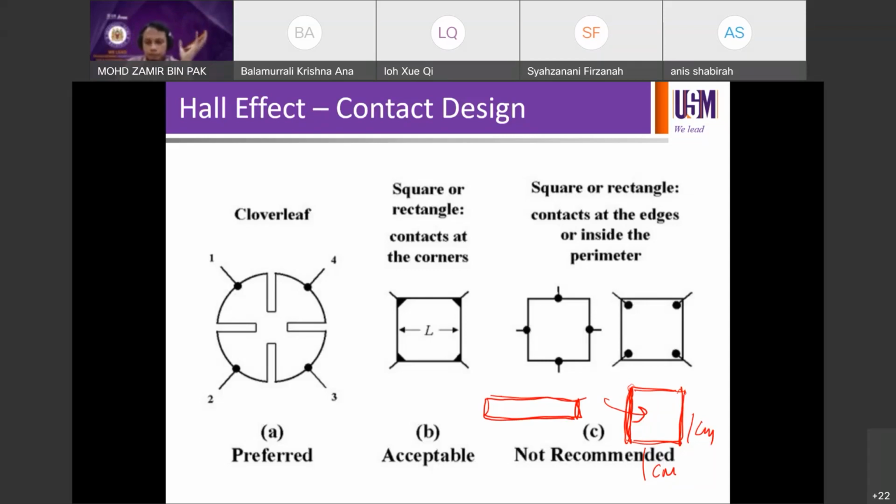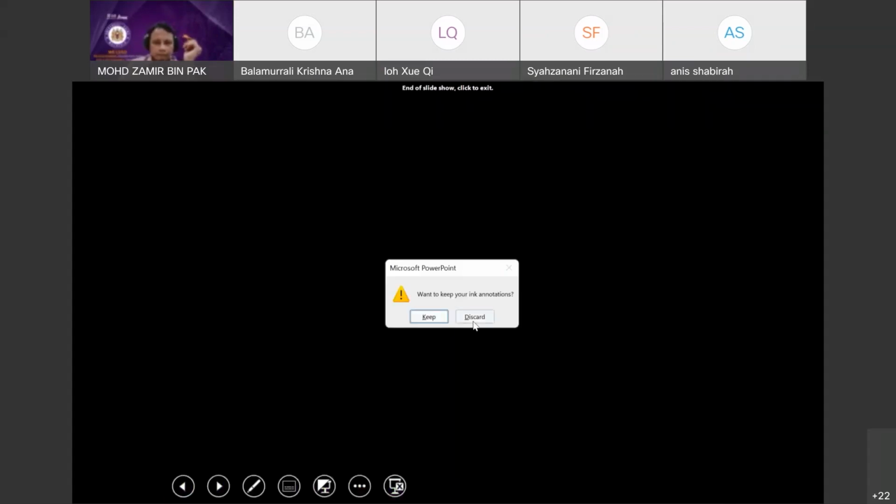So typically, if you have a square sample like this, you need to evaporate, or incorporate, the metal contacts on the sides, on the edges of the sample. For example, say your semiconductor here is silicon, so you might want to evaporate or use some other process like sputtering. So you're going to learn this in more detail in, oh, hold on.